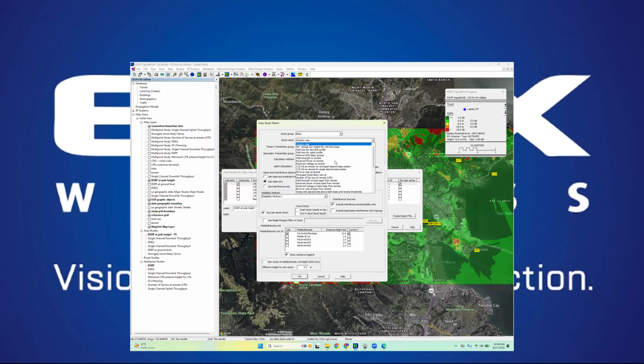If I say I want to do the C over I ratio for primary group to secondary group TXs, I could create another transmitter group of the interference generators and treat those as like an uncoordinated network in the same band. And it's going to give me my C to I ratio considering those interferers.